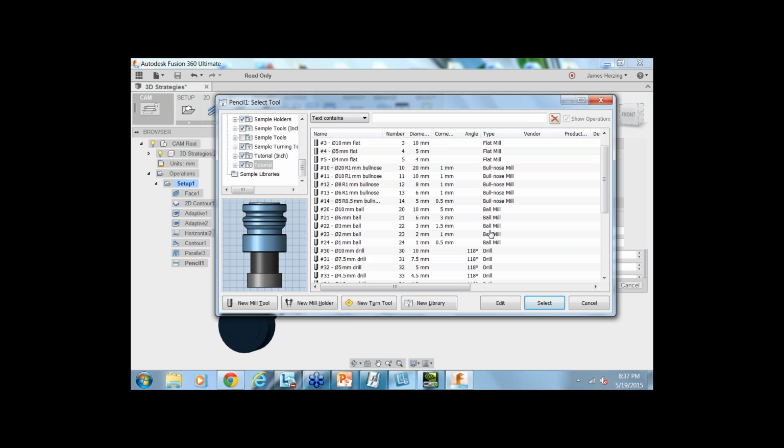But typically, 3 tool changes for something like that would be a bit much. 2 would probably be more effective. Or using 1 tool change with the smallest tool and then using a much larger clearance tool for the main pocket. And often we have control of the 3D model, so you may want to just change the 3D model, to change the design so as not to need such small tools. Assuming that the design can get away with such changes. Yes. Yeah, typically. Okay.